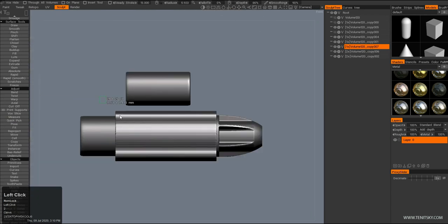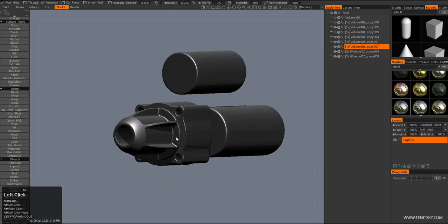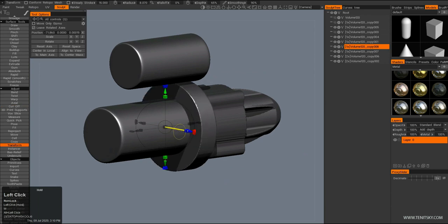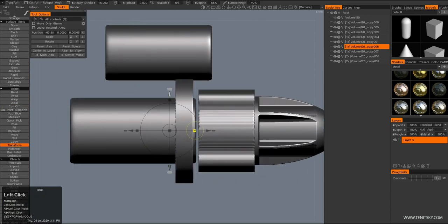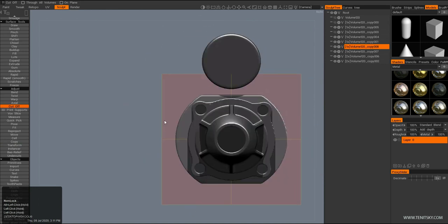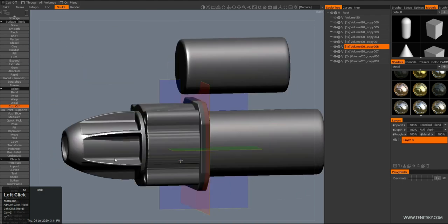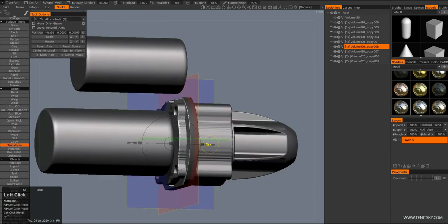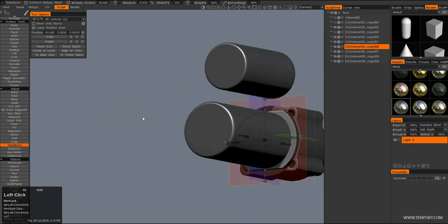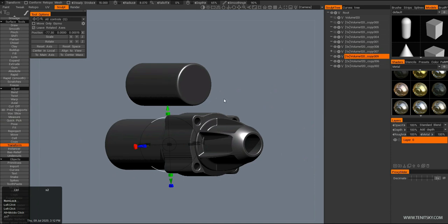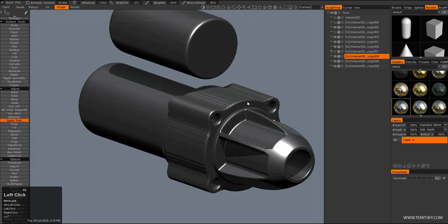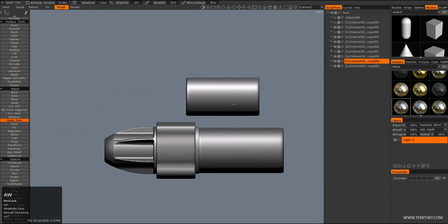So you can see it's a fairly low res cylinder. I should have really increased the density here, maybe like 3 times, so I wouldn't get those artifacts, which I had to later get rid of. And you'll see me having little artifacts here and there, like slightly imperfect mesh. It is possible to get rid of it. It is possible to do cleanup operations, trim off the edges and all that. However, usually it takes more time to do that. So I quite often just leave it. It's just good enough. Don't want to care about it. However, I did fix that 4-hole part later on a little bit.